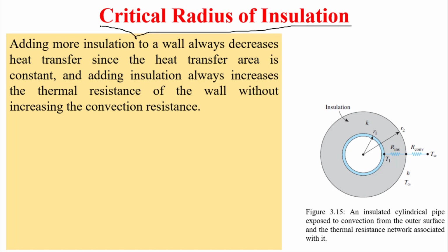Now, the last topic here in spherical and cylindrical is the critical radius of insulation. At the beginning of this chapter, I demonstrated the objective of this chapter, and one of the objectives was insulation. If we increase the thickness of insulation, it may increase heat transfer. And at that time, you asked me why it increases. We add insulation to decrease heat transfer, to minimize heat loss.